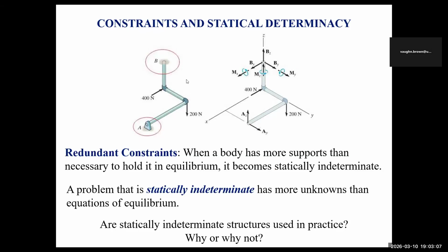So you're going to see what we're talking about now. So look at this system again. So you have one reaction here. It is pinned up here. So anytime it is pinned up here, you have reactions in all different directions, right? And you have moments in all different directions. That's B. What about here? This is a simple journal bearing, so it's only what? 2. Then you have a reaction here, a reaction there, just as you had them there. So they are redundant constraints.